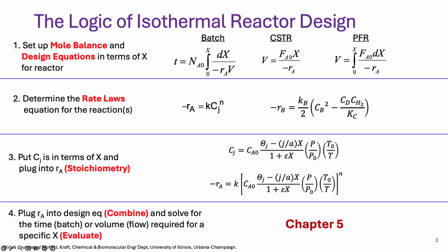The general approach that we'll be using will be independent of the type of reactor involved. In each case, we'll be starting with the general mole balance. Now, of course, that will vary depending on if we have a batch reactor, a CSTR, or a PFR. But this is our starting point. We use our design equations for the appropriate reactor.